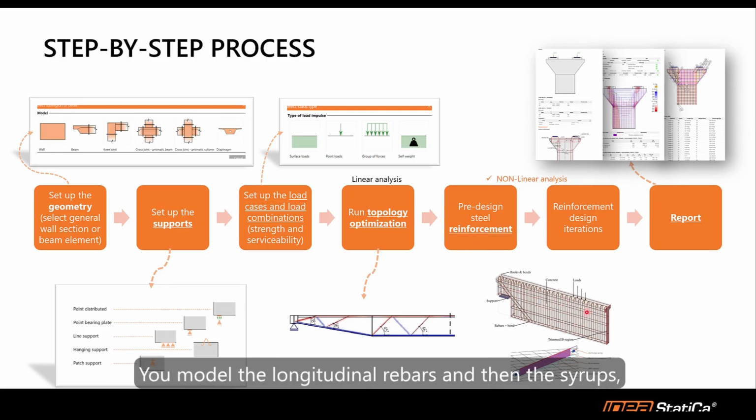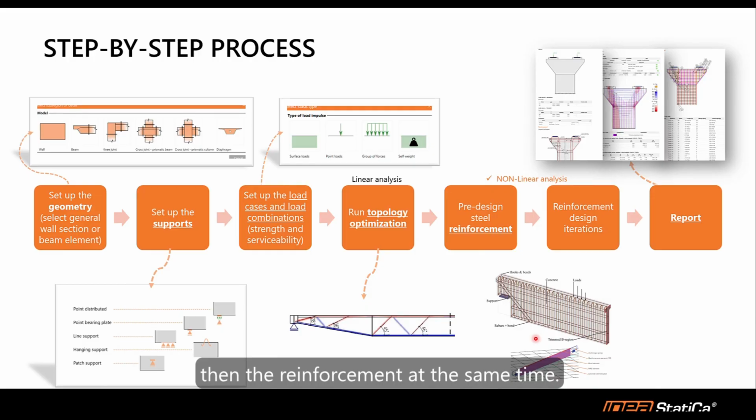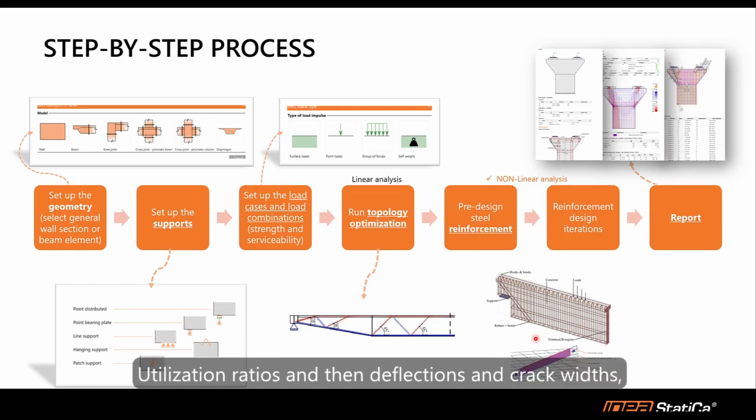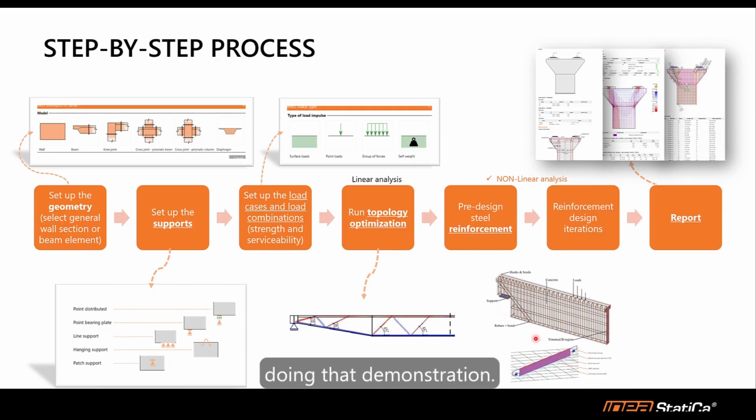You model the longitudinal rebars and then the stirrups, and then we can run a nonlinear analysis. That nonlinear analysis will consider the concrete elements and the reinforcement at the same time. After you verify utilization ratios, deflections, and crack widths, and everything is passing, you can create the report. So you will see this process in the application while I'm doing that demonstration.